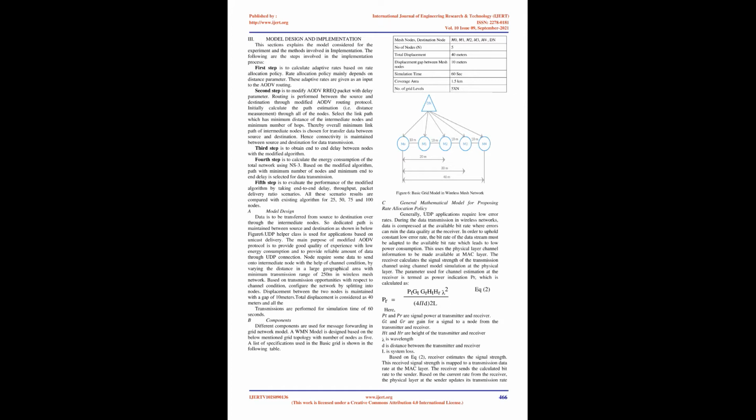The total current is calculated as the sum of currents from all device energy model components attached to the energy source. In Ns3, initial energy is given by the get initial energy interface. After calculating the energy consumption, remaining energy is calculated by the interface get remaining energy and then gets updated to basic energy source.